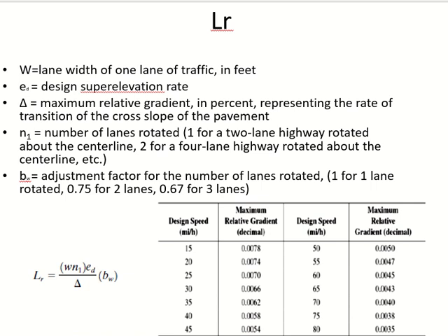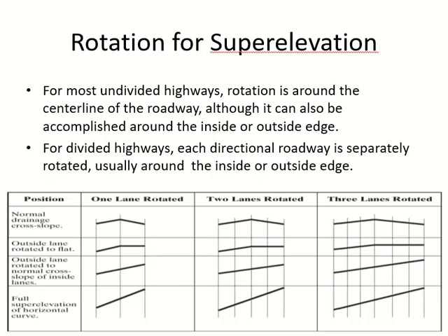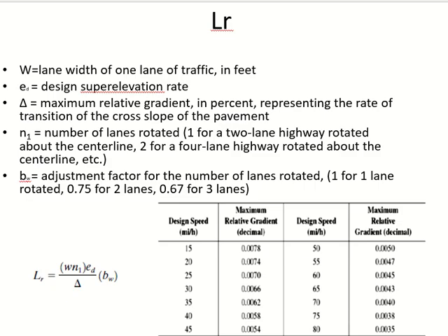Equation to calculate superelevation runoff. Superelevation runoff is this part, from the second to the last. This is superelevation runoff. So how do we calculate it? This is the equation. I need the width of one lane, and the number of lanes rotated on one side, from the reference.